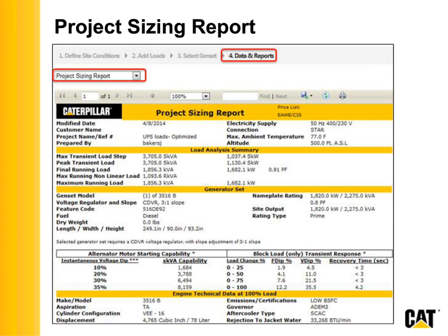Do you remember that I mentioned that SpecSizer is a full transient response tool? These are not fudge factors that we use for transient response. We actually factory test our Gensets. Actual iron, I get that transient response. Remember I mentioned that we get it at not only a standard slope, but an optional slope. Well, that is loaded into the tool. So here you see the transient response of your selected Genset at 25% load change increments.